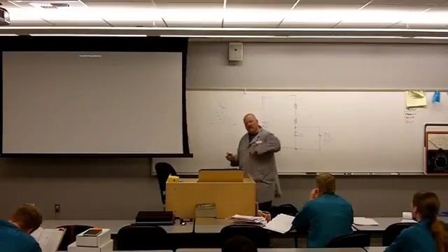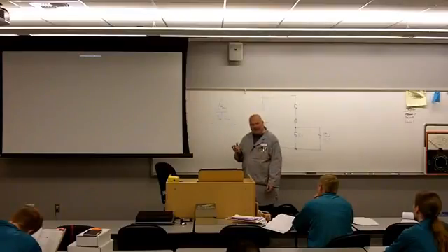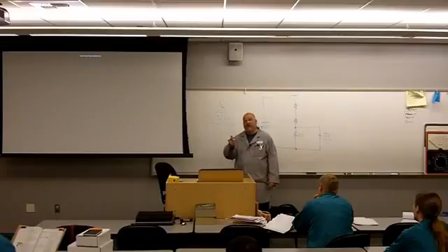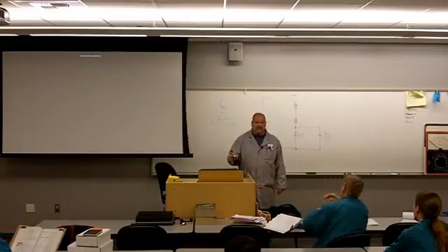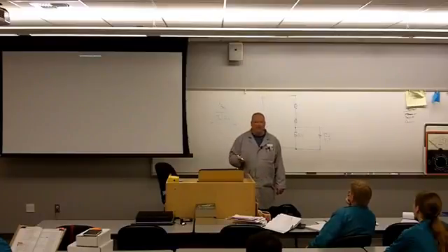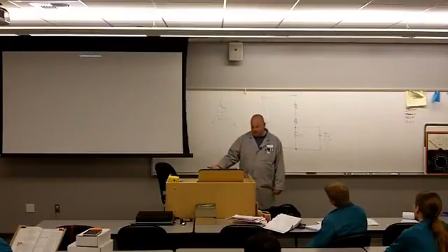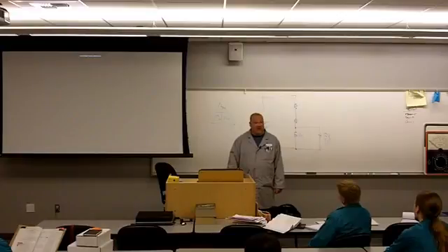So how much current is going to be required to power that radio when I key the microphone and broadcast out 5 watts? And that's, by the way, the maximum you'll ever consume in a CB radio. If it's a 5 watt radio, the maximum you're ever going to consume is when you're transmitting. If you're just receiving, that doesn't consume much energy at all. It's when you key that mic and transmit that you start consuming the most power. So I'm thinking worst case scenario here.